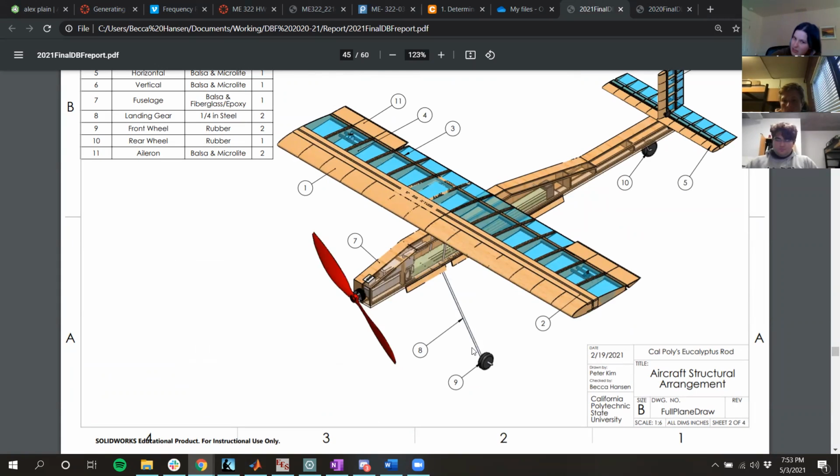I'm thinking a carbon composite. Because I think it would be a good test, once we can get in the lab, to do a little carbon composite wet layup. We saw USC did it last year. And then I think you should be able to bolt it in from the bottom to a hard point on the fuselage or whatever. I think that'll be a good option. We can swap it out in multiple prototypes.